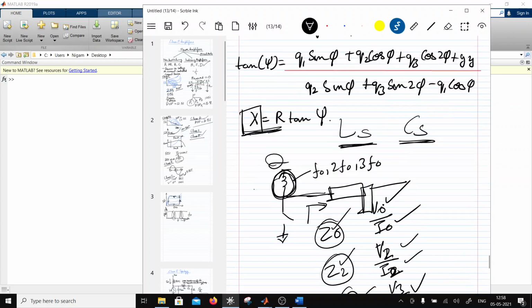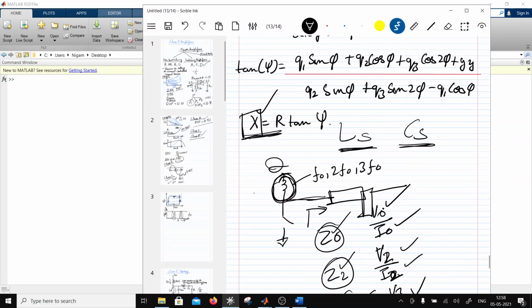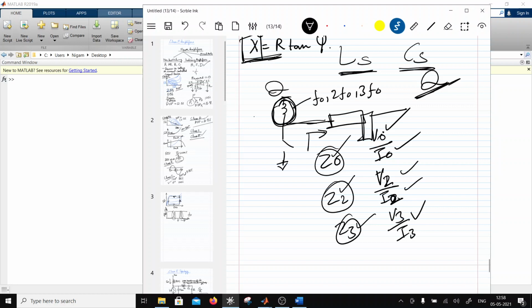So even if you have a jX, which is basically depending on the Q of the network, and we haven't discussed the Q of the network, you can still design a class E if you know the fundamental impedance, the second harmonic impedance and the third harmonic impedance, and all other harmonics are insufficient, right? So you'll be able to design a class E just with this. But then it is good to incorporate Q into the equations to be able to design class E. So in the next session I'm going to design a class E for any Q, right? And that will be the complete design, right?